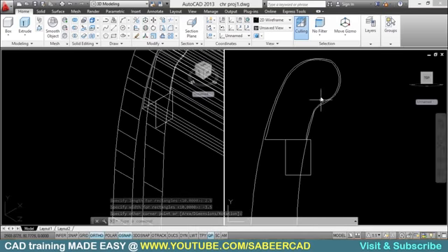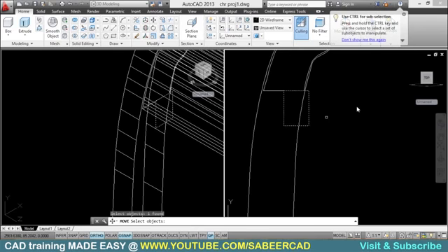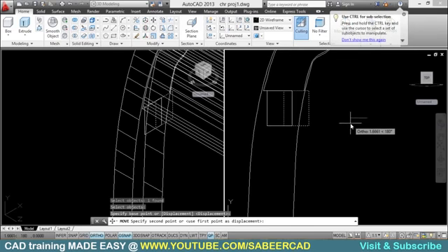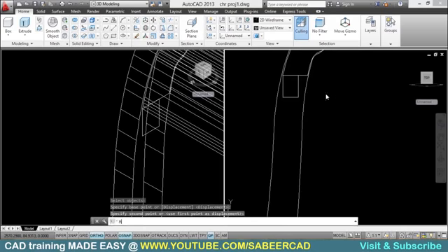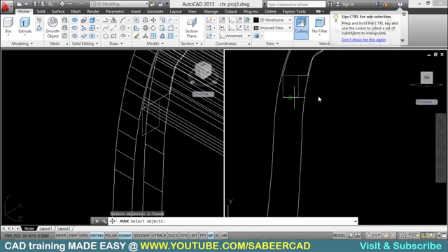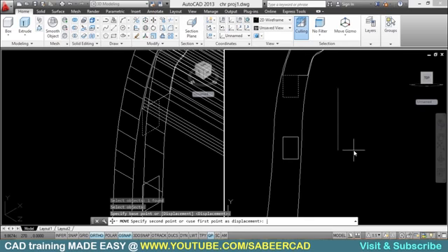Now I'll position it properly and I'll move it to the right location. So I'll click on move command and I'll select this rectangle and I'll move it somewhere over here. Okay, then I'll move it straight down through a distance of 10 cm. I'll select move tool again, select this rectangle. Base point is this point and distance is 10 cm. So I'll give the value 10.